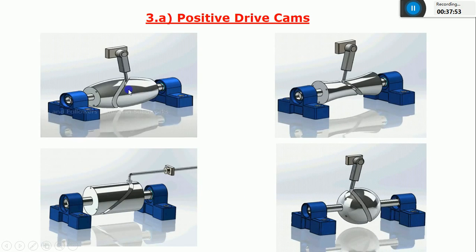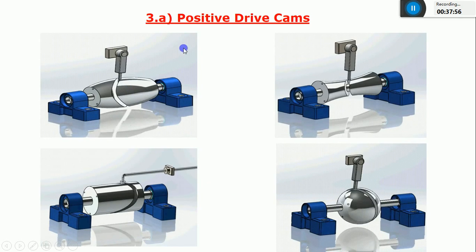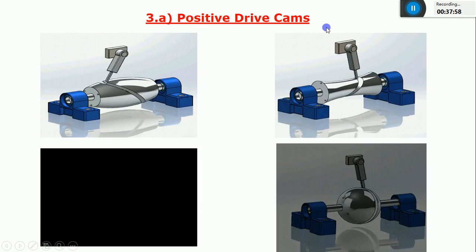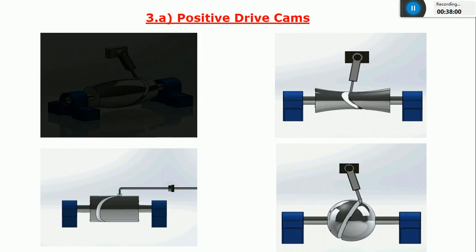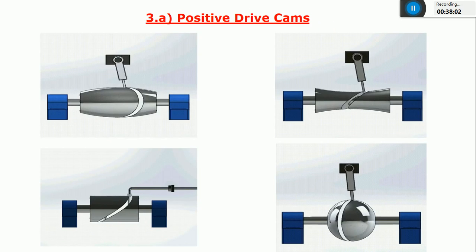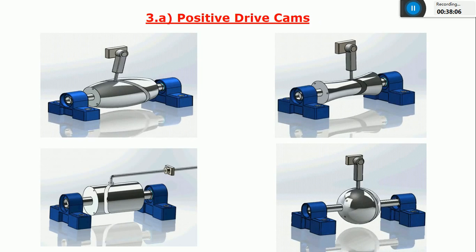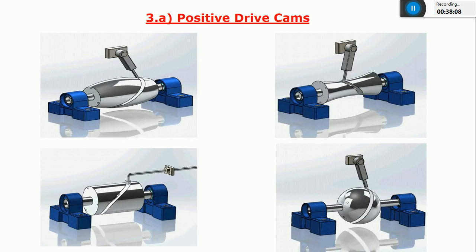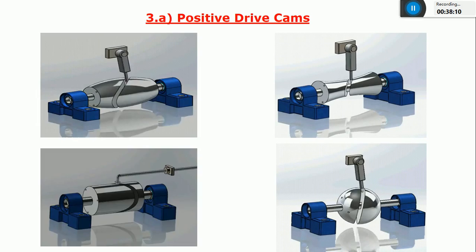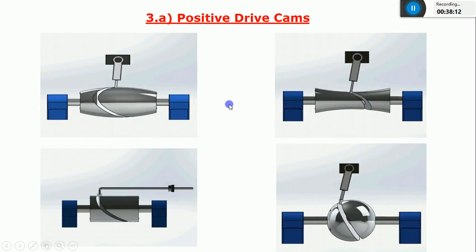It means all these four types of cams come under positive drive cams. In this type of cam, there is no requirement of an external force or a spring force to maintain the contact between cam and follower.